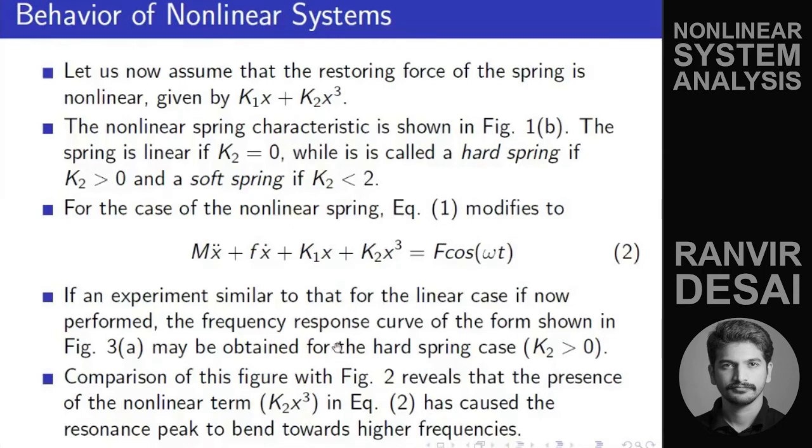In this case it is applicable, but it will convert the system into a very complex representation in the Laplace domain, which is not comfortable for you. It will have a non-proper transfer function. That means the order of the numerator is more than the order of the denominator. So it might create some problems.